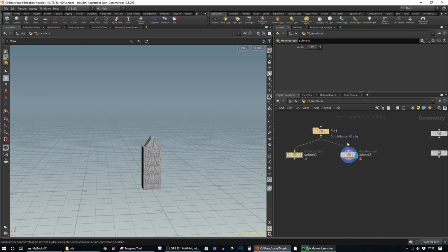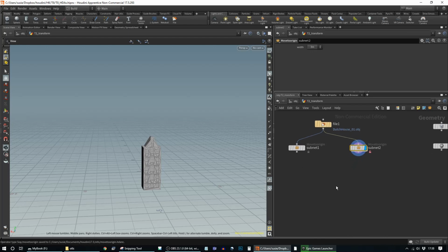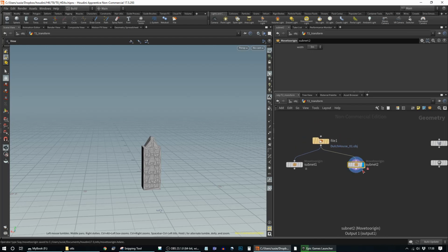The other thing you should be aware of is that if you haven't matched the current definition, then the changes that are in here are saved in your file. So it's possible to have a file with some edits to your digital asset that aren't saved on disk. And sometimes that can be a bit of a lifesaver if you accidentally overwrite the one on disk. You can go back to an earlier file, find those changes and save those ones instead.